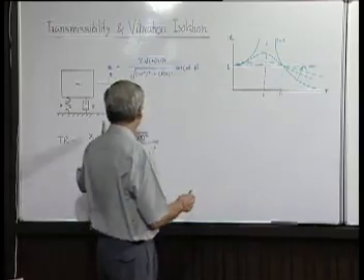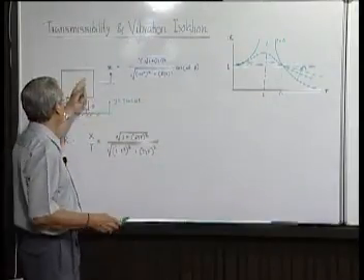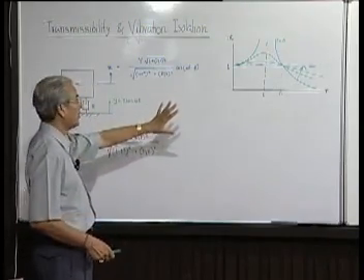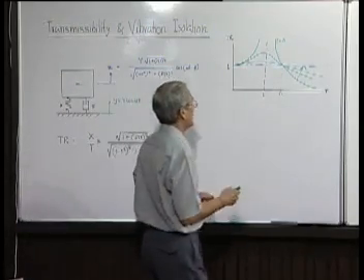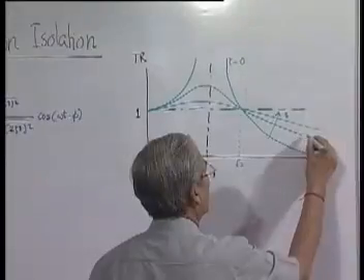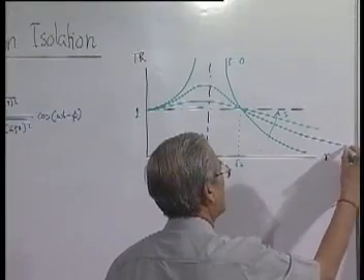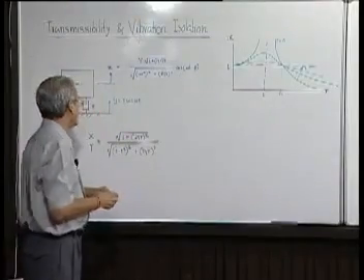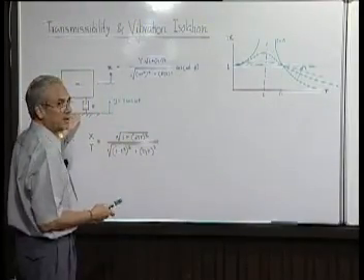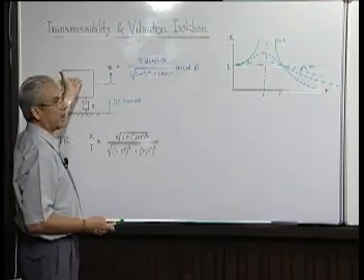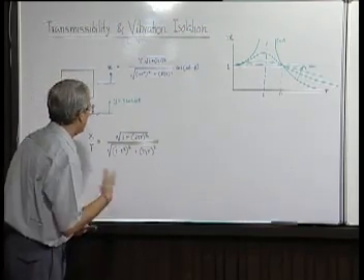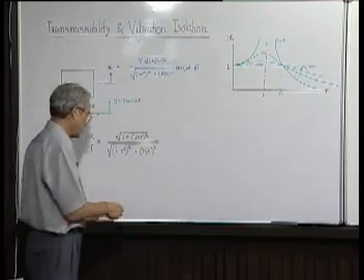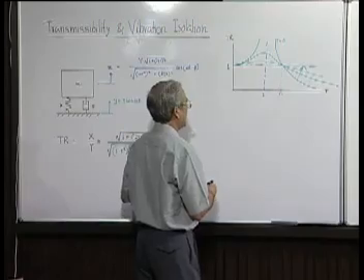That means whatever disturbance I am giving, the same amount is being produced here. But if you can design the system in such a way that r is large enough, operating somewhere here, then transmissibility will be a small fraction, maybe only 10% of the motion given to the ground is being transmitted.